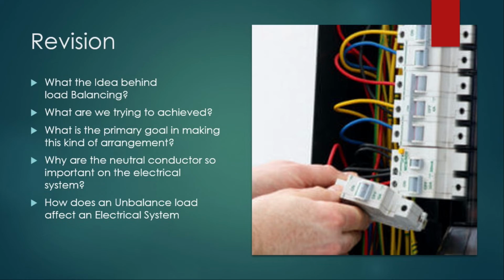from a single-phase or two-wire, three-wire, or four-wire system, three-phase circuits. So the arrangement should be that when we lay out our loads, we create a condition where the neutral current would actually return to a minimum or zero. So that is the key importance of making the right arrangement.